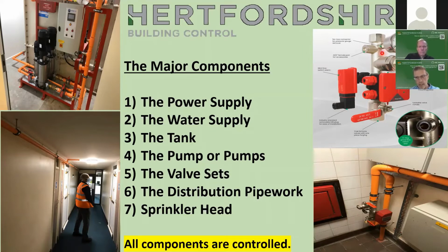So the valve set is one of the big changes in the new code. Virtually all of the valves are controlled, and you need interfaces that go back to the fire alarm panel. So there's not a possibility of somebody turning off one of these valves and then a fire occurs. And of course, there's no water supply.